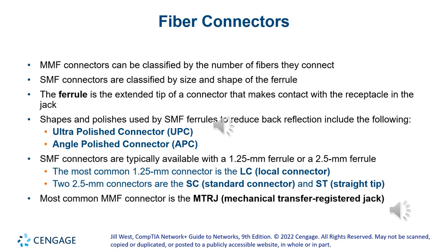Now, on the fiber connectors, don't be deceived. Fiber connectors can be the same for single mode and multi-mode. There's no such thing as a multi-mode connector or a single mode connector. They could be the same. The only difference is how they accommodate the core, whether single mode or multi-mode. And the tip, which is called the ferrule. The ferrule is a little tip that extends where the fiber goes in, and it will be different sizes. Of course, for multi-mode, it will be thicker than single mode.